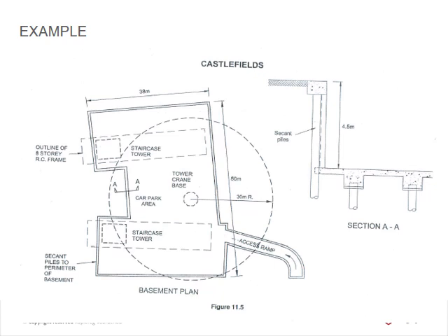The excavation works in association with removal of spoil to reduce the ground to the required level, allowing construction work to basement piling and floor to commence. Construction work includes pile caps and bases within the basement area. The basement excavations take place between the secant pile wall. Access to the 5-meter deep basement is via the proposed access road. So here's the access road that they've got planned.